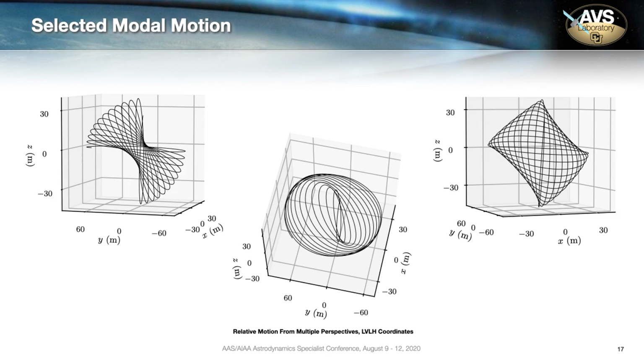It's complex and differs greatly from anything you'd see with Clohessy-Wiltshire dynamics. It starts out with very little z motion, but then the relative orbit rotates out of plane and distorts over time. It also becomes thinner in the x direction, but it's bounded and well followed by the nonlinear dynamics. So multiple spacecraft could target different scalings or phase shifts of this modal structure and would remain in each other's vicinity for long time spans. So this is a well-behaved, bounded, and comprehensible structure that could be useful for formation design.